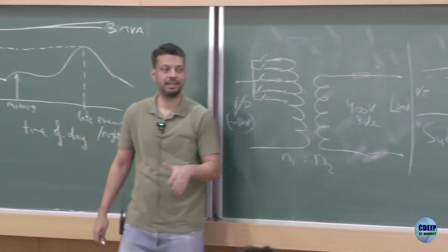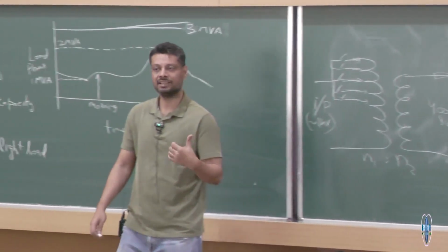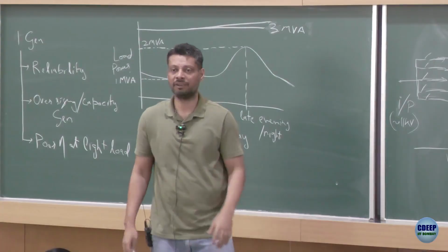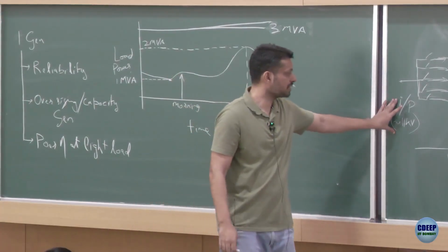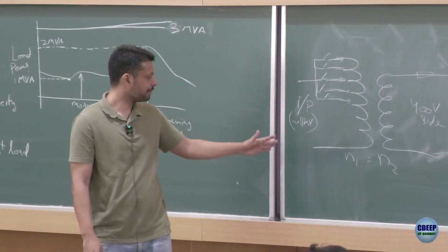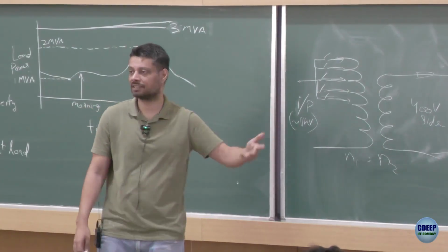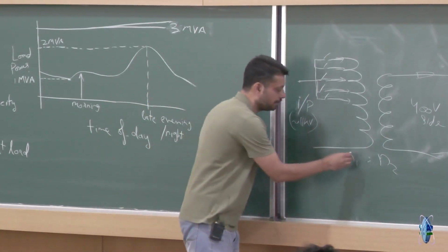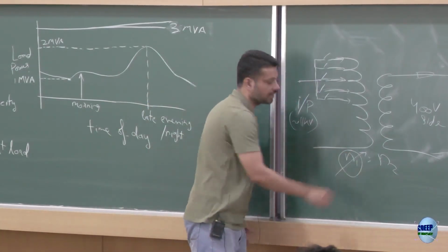Depending on that, you can write a small logic, and this would make sure that the voltages are fairly well maintained, irrespective of the fluctuations here, irrespective of the load fluctuations. Yeah, and N2 remains the same, we change N1 so that V2 can increase or decrease. So, we change N1, not N2.